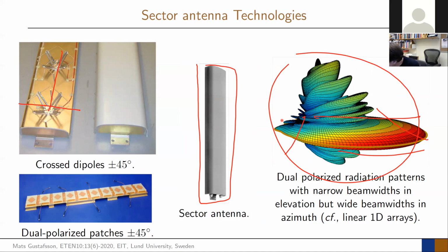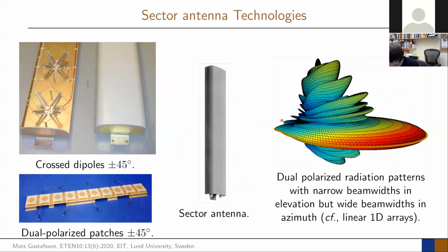These are some crossed dipoles that you can see up here. You can see some feeding coming up there, and some antenna elements sticking up here. It takes both polarizations, in many cases plus minus 45 degrees, to equalize horizontal and vertical. It means that both channels would work the same if you put them at 45 degrees. There could also be patches inside of them, another type of antenna.